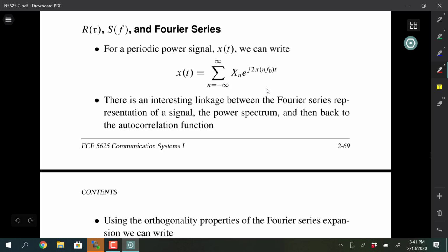And Chris experienced that in the project for modern DSP. It was GPS tracking, right? And that uses not an autocorrelation, but a cross correlation. Auto is when you take the signal you have and correlate it with itself. Cross correlation would be like in a radar application.